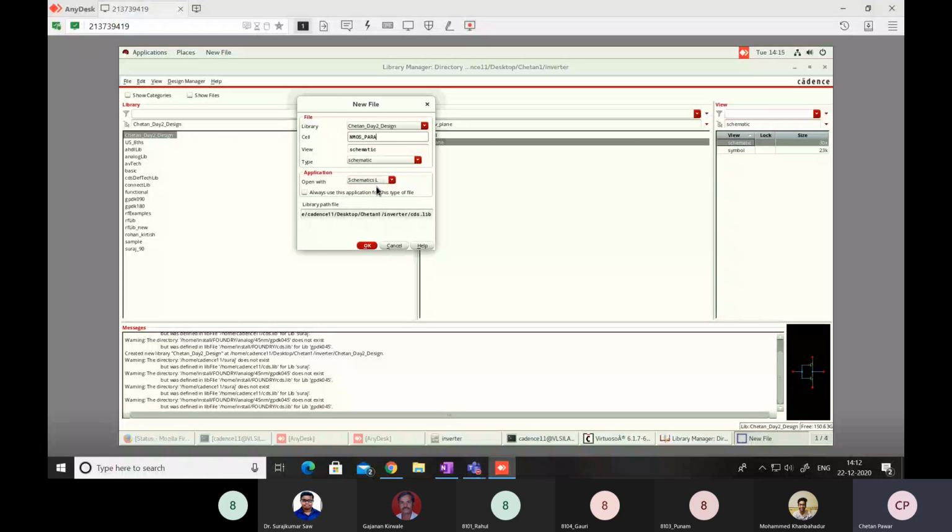You just check that. Don't give an unrelated name. Only give the relevant name like nmos parametric analysis. Don't give inverter parametric analysis. Give nmos. Cell view. Rahul, cell view, not library. File, New, Cell View.